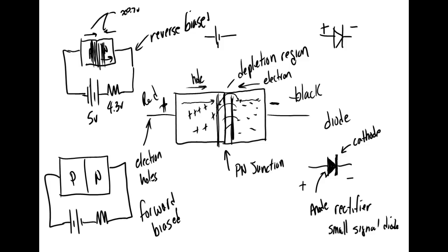The p-n junction is really neat. This is our check valve of electronics. Tubes used to do it, which is pretty neat. Tubes worked off an electrostatic charge. Vacuum tubes had to be heated to cause them to work. So if you've ever been involved with vacuum tubes, you'll see a little orange glow in there where they heat the cathode. So they literally have to heat the cathode to make it work. And it has to be done in almost a total vacuum. Usually the tube is made out of glass.